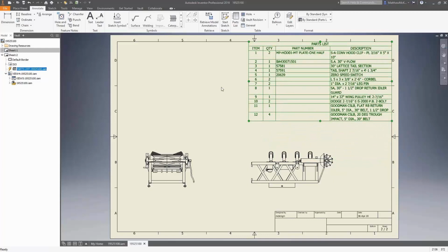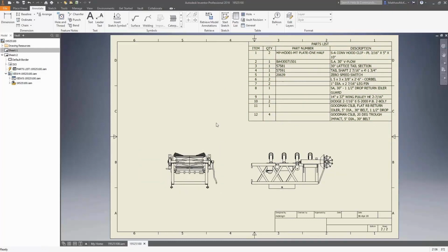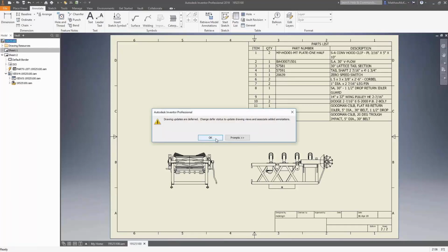So what you can see here is we're really just trying, where possible, to minimize the information that we're putting on there. We're using simple workflows for how we place our components. We're using view representations where possible in place of level of details, where possible even trying to avoid or minimize the use of those.